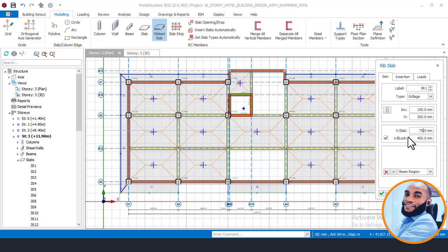And then this place that says X block. The depth of the slab also comes with a rule of thumb, and that rule of thumb is that the depth of the slab should be 1/25 of the span, but that is if we are designing for a large span. Like I told you before, waffle slab can be used either to reduce the load of the building and also to design for a large span, just as we use flat slab.